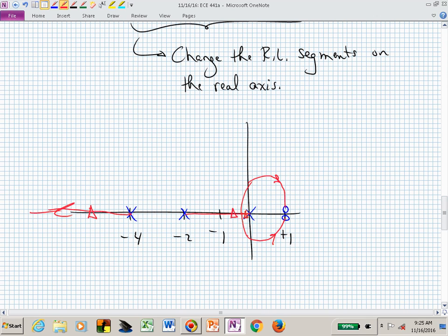So a pole at the origin is marginally stable, but you really don't want to be operating on the imaginary axis, and with a little bit of a gain k, you've now pulled that into the left half plane. We want to live on the root locus. We have to live on the root locus. We just want to pick a gain k to get us into a stable place.